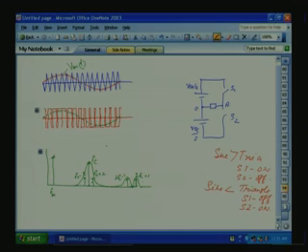So, how do we suppress this harmonic without resorting to high frequency switching? Okay. Like our front end AC to DC converter, with our sine triangle comparison we have got the fundamental amplitude variation control. Now, to limit this harmonic, we require one more degree of freedom. So let us see. In this case, if you see, the output is going between +1 and -1. Okay. Now, let us go to the next page.